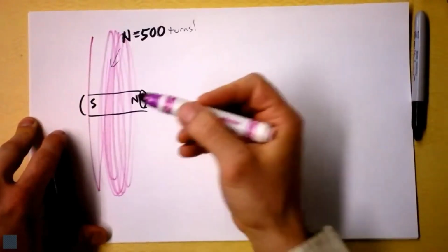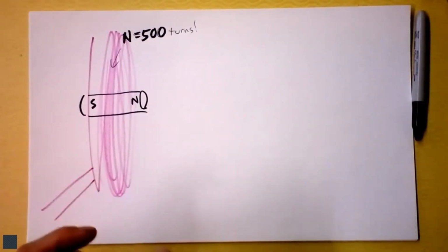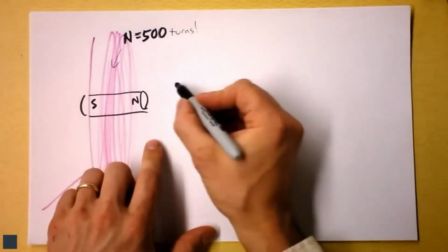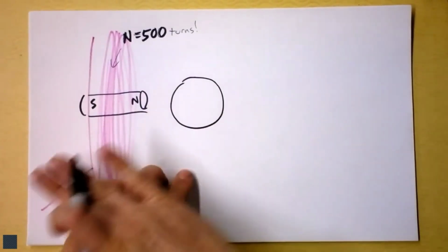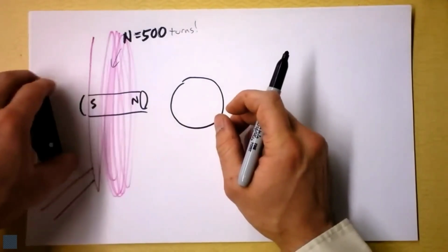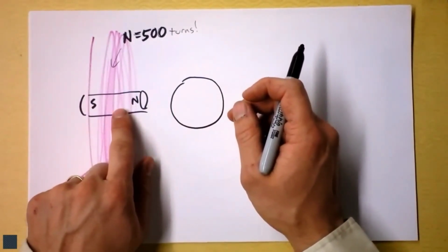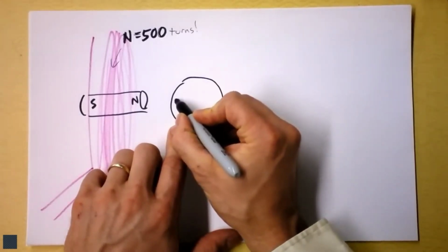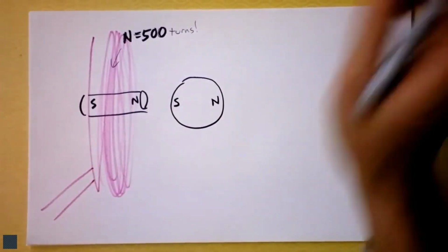Lots and lots of turns. Hundreds of turns, and the coil comes out and goes out, so it's got 2 leads leading from it. But in front of the magnet lies a string, and from our perspective, the guitar string is sliced and would appear right there. I guess it's going to be a little bit smaller, but I wanted to show you that when the string is nearby the magnet, then the string becomes magnetized, and you can bet that it would prefer to have this side be south and that side be north, assuming it's a ferrous material.